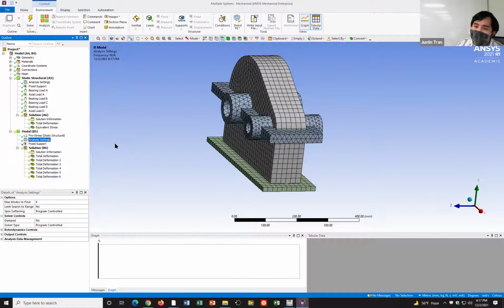What I mean by that is, let's say you start rotating gears inside this. The gears are going to speed up from 0 and go up to a higher frequency from there. Usually once you hit resonance at one frequency, that's something you want to avoid anyway. So for most cases you're only really interested in the lowest natural frequency, which is the fundamental frequency. The other ones are included just for interest's sake. Six is fine, but most of the time you're only interested in the first few.